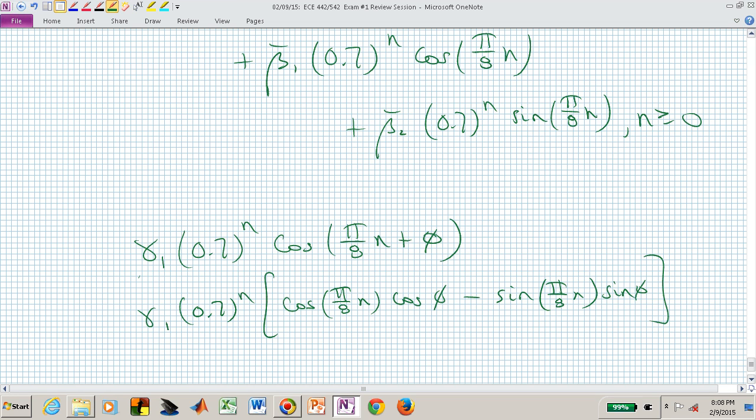It comes from a delay between the input excitation and the output y. That delay is related to this phi, and that phi actually gives rise to a sine piece and a cosine piece. So all you have to know is if somebody starts shaking something with an exponentially damped sine, you generically are going to have the exponentially damped sine and the exponentially damped cosine. You may not know what fraction of each you have, but you're going to have a combination.